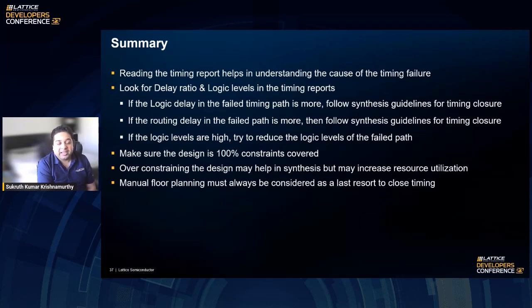Over-constraining the design may help in synthesis, but may increase resource utilization. But it's worth a try. Manual floor planning must always be considered as a last resort to close timing. Sometimes floor planning is too complex that it might not help you much, but you should always consider this to be a last resort to close timing.